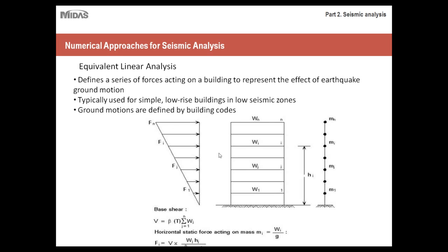So for example, here you have, I don't know how many stories this is, but you have a low-rise building, and in order to create your seismic loading, you just take a force and model it as a triangular distributed load, which increases the higher you go up, because the farther away you get from your foundation, the more flexure you'll experience as you go higher up. But obviously, you're making several very large assumptions when you're doing this type of analysis.